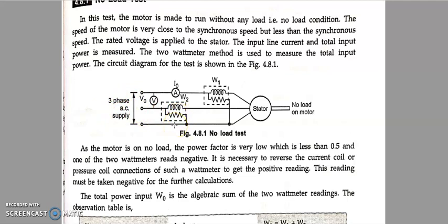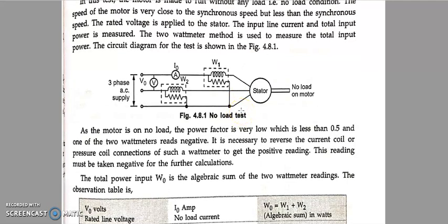So start the motor at the subsynchronous speed. Make sure you apply the rated voltage. Line to line voltages, say around, if it is a 415 volt motor, apply the rated voltage, and make sure they are all AC meters for V0 as well as I0, since I am connecting an AC supply to this. And again make sure the speed is subsynchronous, which means it should run at lesser than the synchronous speed. As it's an induction motor, it runs at the subsynchronous speed itself.